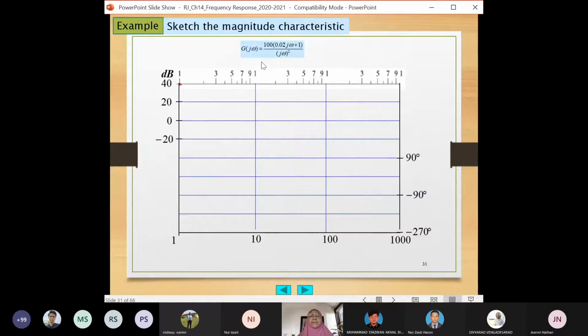Okay. What are the zeros? When you have a transfer function, you have to be critical to know what the components are, the poles and the zeros. So the numerator gives the zeros information, the denominator gives the poles information. So from the zeros and poles, it gives you an indication of what the magnitude plot and the phase plot are.